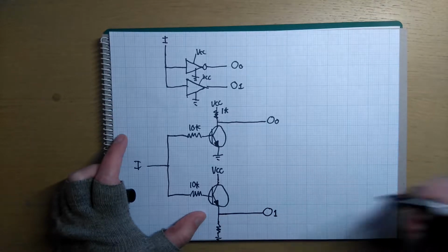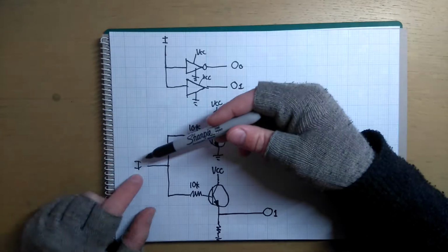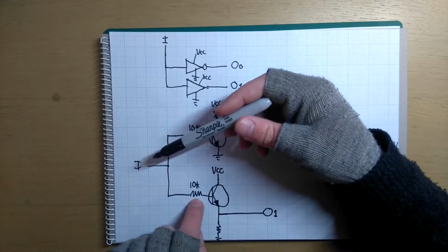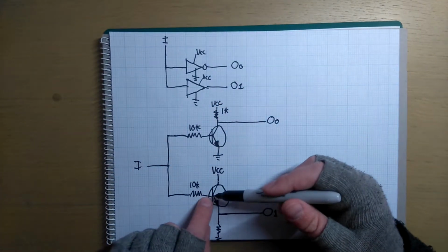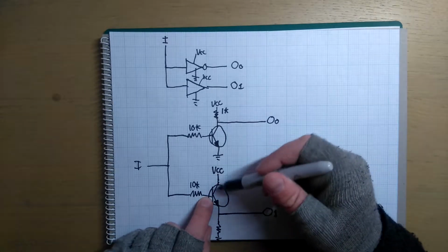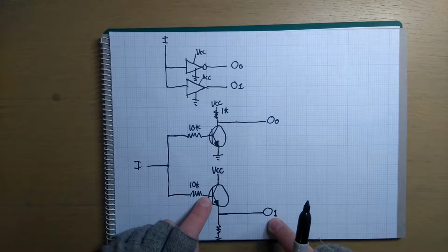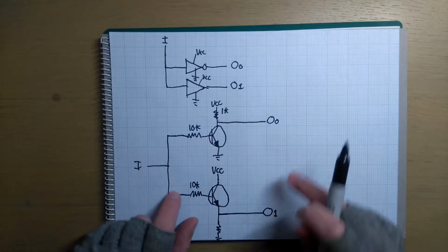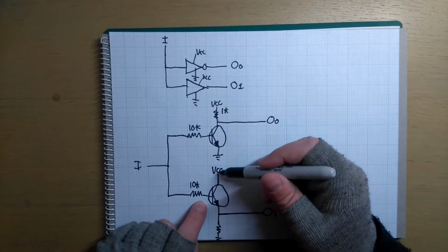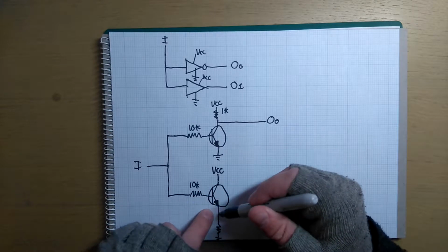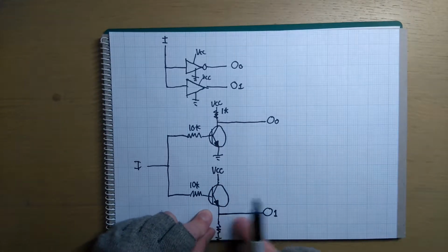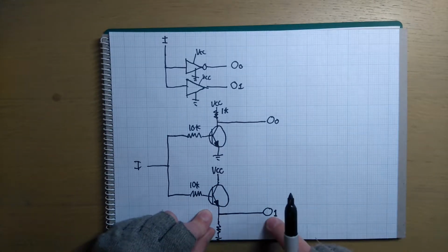Output 1. So what's happening here is that when this is 0, nothing happens here. This is closed. So no power is getting here, but this is connected to ground still. So output 1 is low. When this is 1, the gate opens and allows VCC into here, and because of this resistor it's blocked, so it would rather go this way, so that becomes a 1.